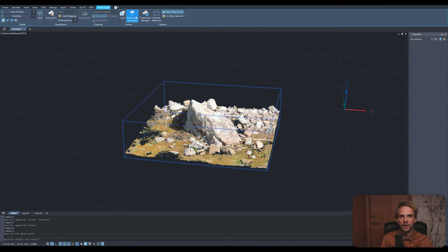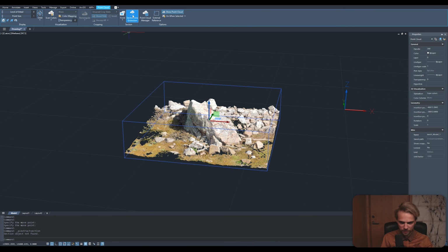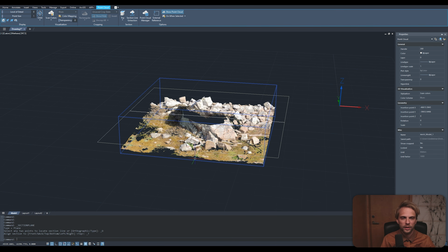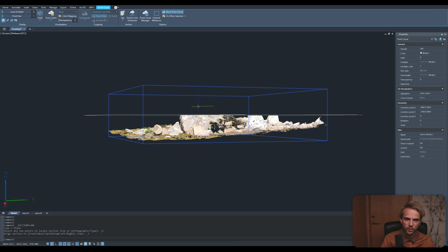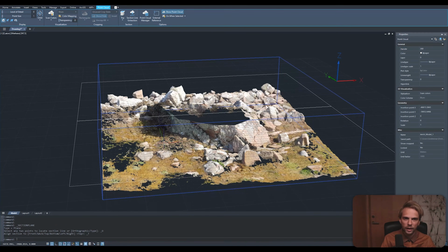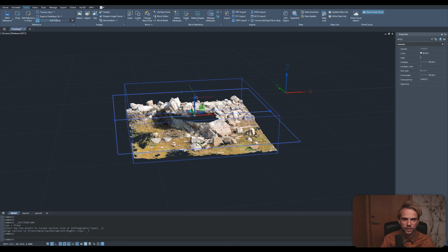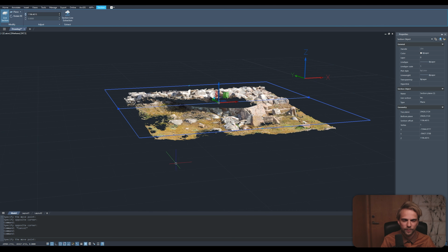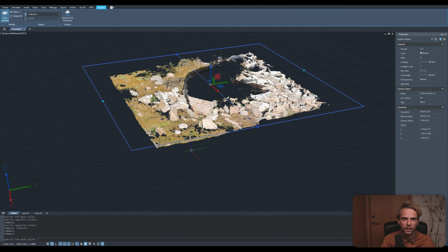There's ways of how you can create, for instance, a section. Apologies. If we select the point cloud here and we choose what's the section height, or is it a top section, a back section, front section, what's the alignment of the section plane? So in this case, I'll choose top section. You can see that now it's cutting through the top of my rock. And in doing so, I can take the section plane, move it down. There we go. Move it down, right, to an appropriate level.